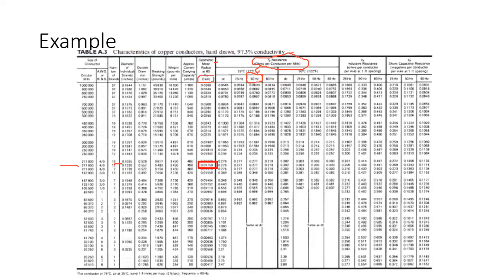So this is a conductor, and they have the test on it. When they do the test, they do the calculation of the conductor, and it comes out like this with strands. So they have 12 strands, and this is the geometric mean radius of this conductor.